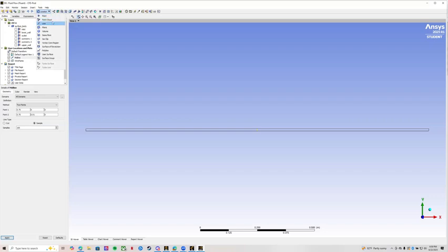You can go ahead and put another line here. This one's going to be called our end line. This is where we're going to put it towards the very end. So that's going to be at that 1.4999. So it's right there at the edge, so we get the best data we can. And then we're going to put it at that height with 100 samples, apply, and you can see it's right there.